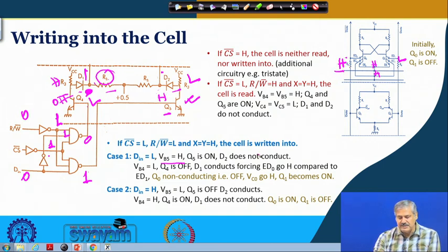Now because of these external forcing inputs that you get over here, that this is high and this is low, what would happen? So this transistor now cannot conduct in this direction. Okay. So this transistor will go off and it raises the voltage over here. So that voltage will allow this transistor to go on, right, and this is low, there is no issue, it is possible.